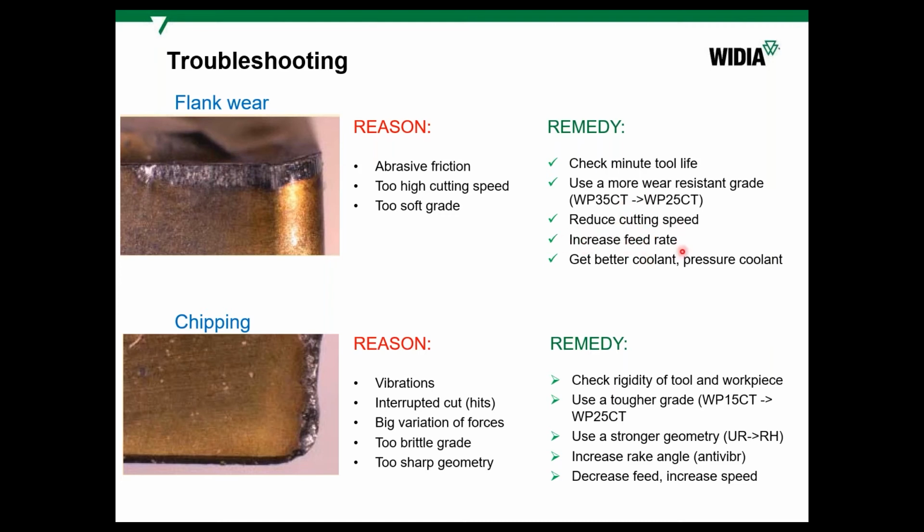Increase feed rate, also sometimes it happens, I mean, like a compensation. We can reduce cutting speed and increase feed rate instead of that. Get better coolant and pressure of coolant.